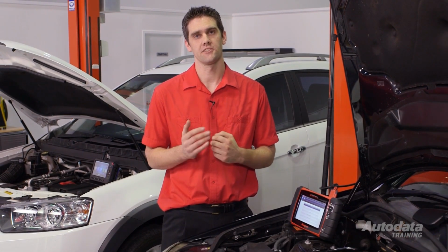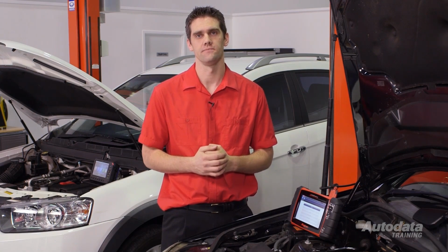When an injector is replaced, the engine control module needs to have the new code entered to be able to compensate for the differences in the injectors. On some engines, if the control module reads a different code to the one stored in its memory, it may not start until the correct code is entered.